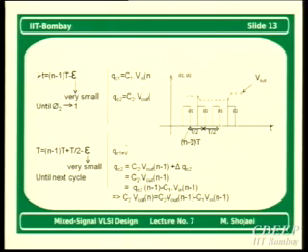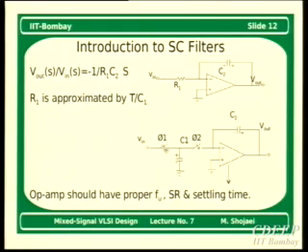So, for example, you can consider you are very close to the edge of phi 1, therefore the signal you will get exactly on the capacitor will be Vin n, which is sampled in that particular phase at the edge of phi 1, when phi 1 goes from 1 to 0. We consider 1 for the case when the switch is closed, and if the clock is 0, then the switch will be open.